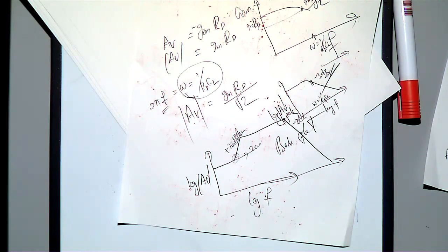Pole identification example. Here you have two capacitances, Cin and CL. Cin is the input capacitance of maybe your MOS, and CL may be coming from some load. We have to identify the poles. Why do we need to identify the pole? Because if you identify the pole, you know where your frequency response is suddenly changing.